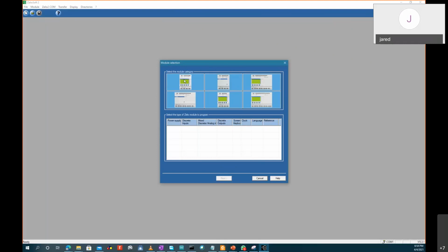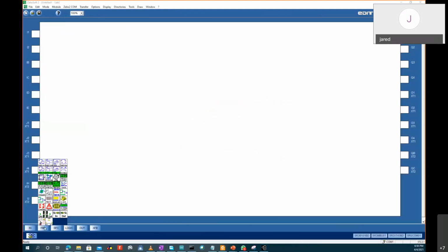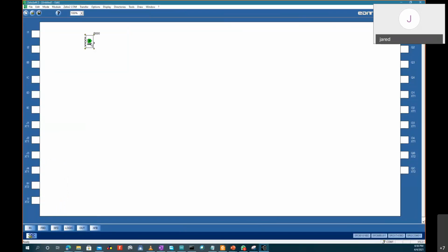Now this is just FBD. It does not use ladder, it's advanced. For advanced functions, you can only deal with the FBD because FBD minimizes the program size. So you see, this is an AND, and I pick I1, I2, I3, I4, and I bring the slash here.